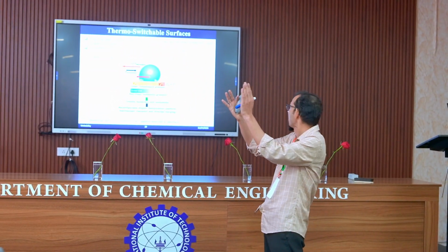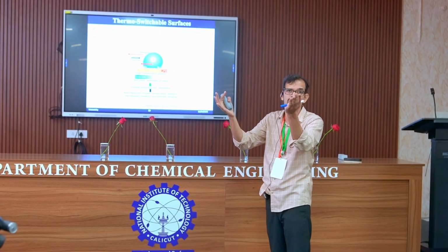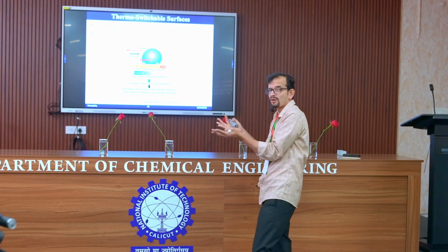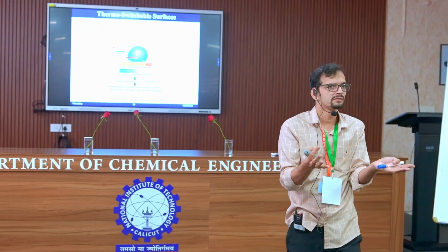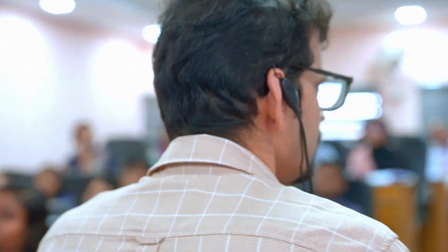The forces acting are the wettability gradient, contact angle gradient, and a Marangoni force. How does the Marangoni come? Because of the surface tension, okay? Because you are changing the temperature, the surface tension is also changing. That also has a contribution in the contact angle, droplet flows, and all beautiful physics is there, okay?